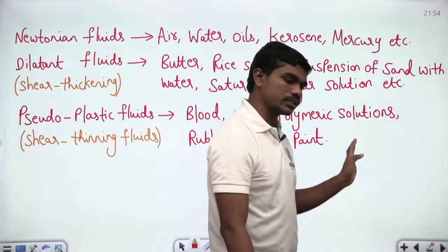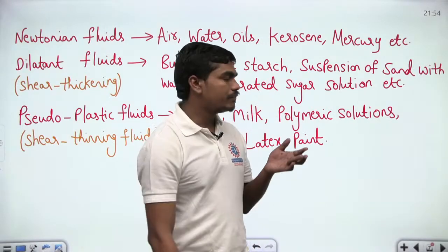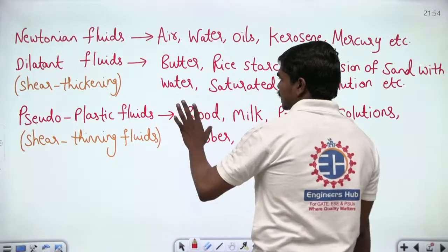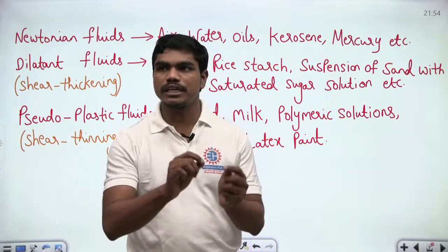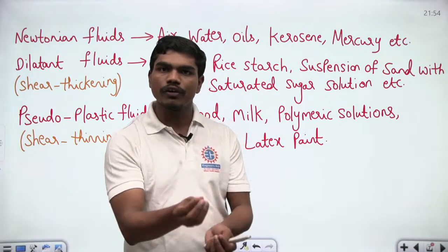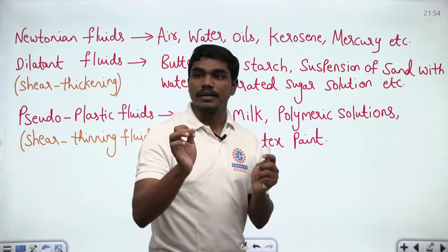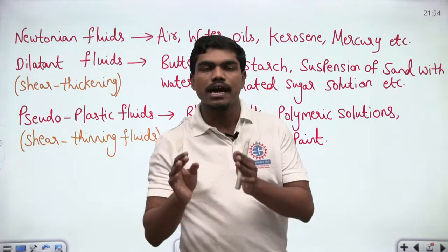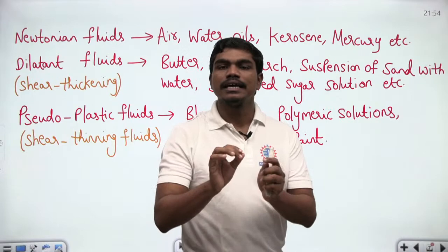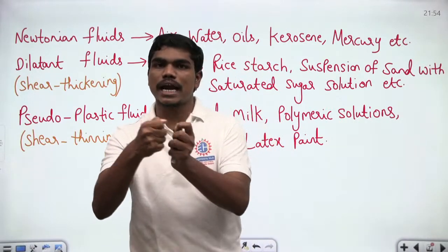Latex paints, correct? Now if this is the case, we have studied the definition of fluid as the substance which deforms continuously under the action of infinitesimally small shear stress. But in actual cases, there are a few fluids named viscoelastic fluids, and these need a certain initial yield stress to start their deformation.